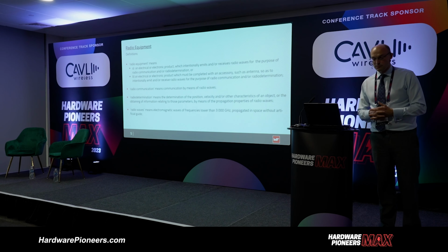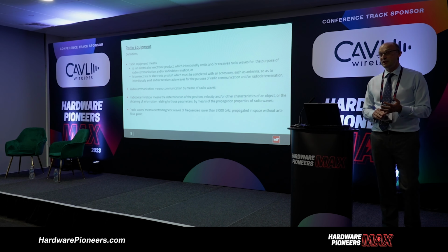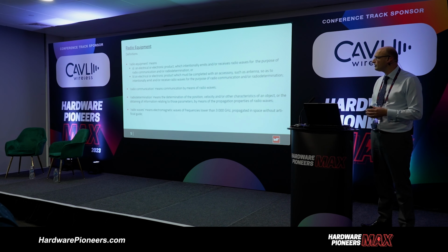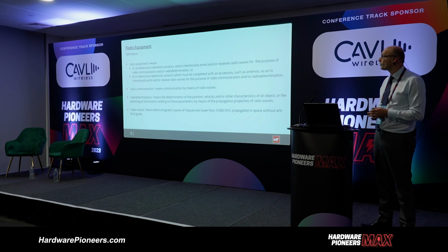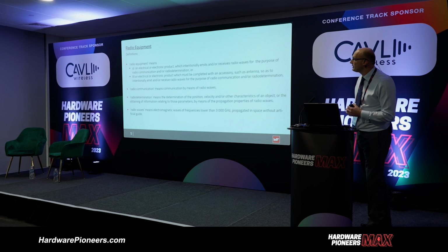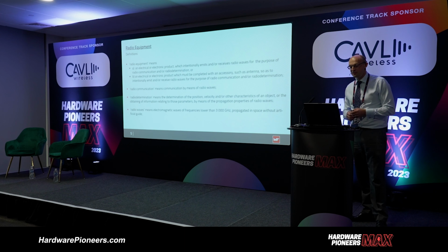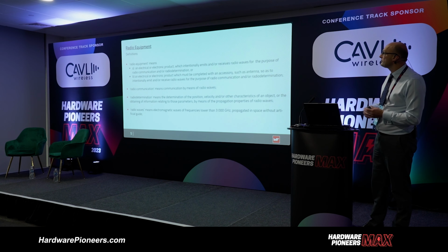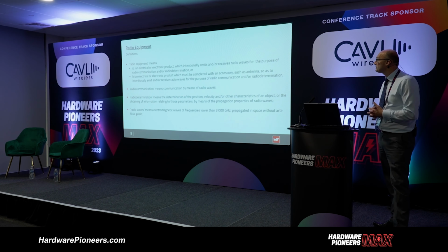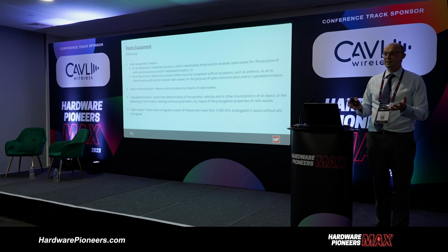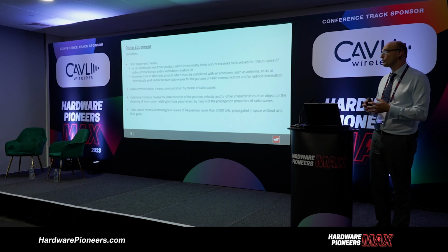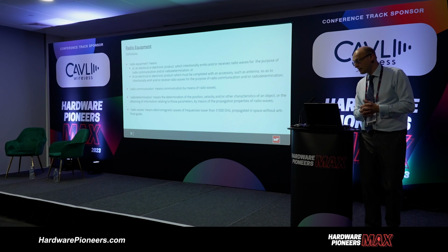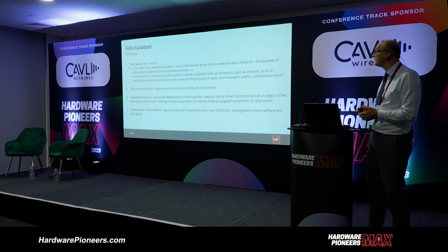So when it comes to radio equipment, we'll look at the Radio Equipment Regulations for the UKCA and the Radio Equipment Directive. And when you look through the actual definitions, here are the terms of what is radio equipment, what is radio communications, radio determination, and radio waves. But interestingly here, radio equipment is an electrical or electronic product which intentionally emits or receives radio waves for the purpose of radio communications or radio determination. So when you take your pre-approved RF module and place it into a piece of equipment, that is in effect what you're now making the end product into: a piece of radio equipment.